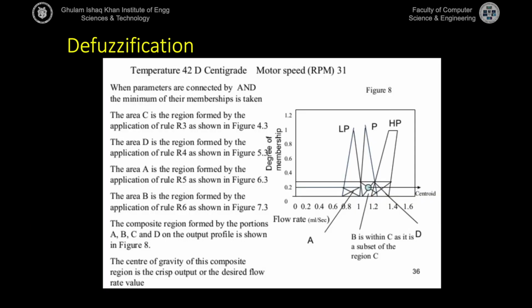So with that, this is the exact example. I can possibly give you any two parameter values, and you need to be good enough to look at the rules yourself. You need to identify the regions using those rules. You need to identify the membership function values. You need to find the minimum of those membership function values, and using the minimum function values, you should be able to find the interesting regions for your analysis.